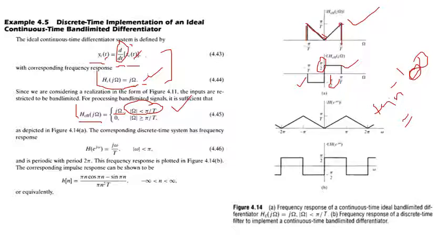So we have the effective magnitude response of a continuous time system, we have its effective phase response. Now we are converting that effective response to discrete time system. So you know what we have to do, we just need to multiply this with t. So it's just like scaling. So we have scaled this, and this figure and this figure is same, but in discrete we have periodicity.